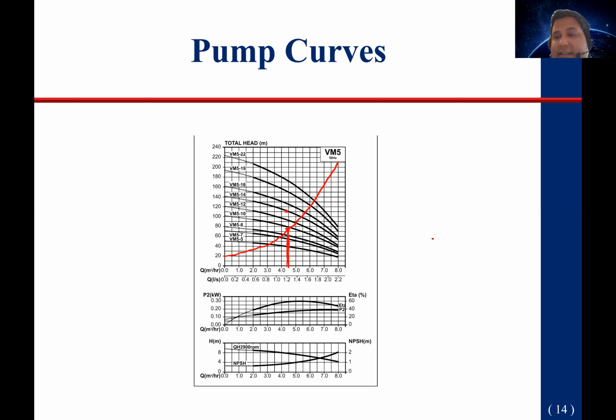It's so important when you're considering design aspects of choosing pumps, the trade-off between efficiency in the pump operation and the flexibility as far as it comes to modifying the flow rates as well as scale up potential. We'll talk about that a lot more in design too, and how if you're going to be limited in your scale up by your pumps, there's very little you can do besides getting new pumps. There's some things you can do to modify it, but at the end of the day, you have one of two options. You change your pump curve, which means you change your pump, or you change your system curve, which means you have to go back and look at the flow design.